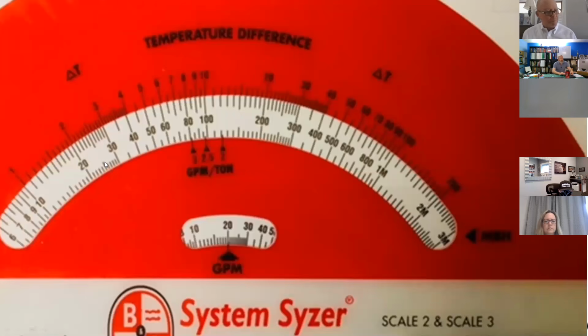And so, I'm not sure if you guys have seen this. I think a lot of you might have. We actually did a class last week on the system size, just how useful a tool it is. So I'm just taking this to use it as an example. When I use scale 1, a lot of times I'm looking for GPM. In this quick example, he's saying, I know the GPM. I want to move, in this case here, this white band is listing the BTUs per hour in thousands. So when I find 400, I'm looking at 400,000 BTUs, and I'm just reading straight up. And what I'm looking at is the necessary delta T to deliver 400 MBH with a flow rate of 20.